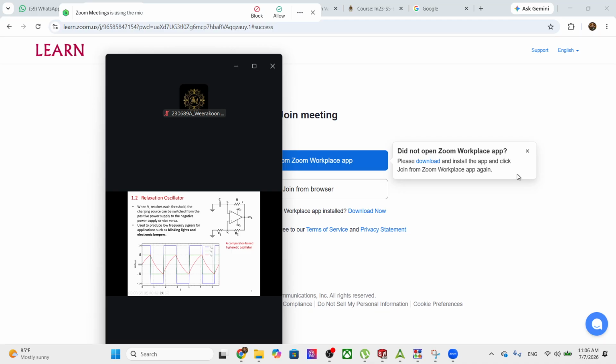So the time constant RC, when you calculate, you can reduce the R and increase the C, or you can reduce the C and increase the R. That is going to decide the current on this path. So it is not that you can choose any component you like. You have to make sure that the current through this path is significantly higher, at least 100 times higher compared to the current through this.